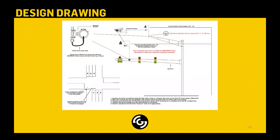All right, so this again is still a part of the design drawing, or the intersection design guide. This is an engineering standard that you can use in your submittals, in your plans. It gives just a good overview of mounting locations for the camera infrastructure. You can see up in the top left how the Cat5 cable would be run and come up through the mounting arm. And on the bottom of this, it gives you the same rules of thumb as far as 30 feet high, 75 feet from the center, and things like that.